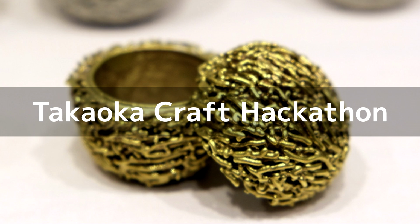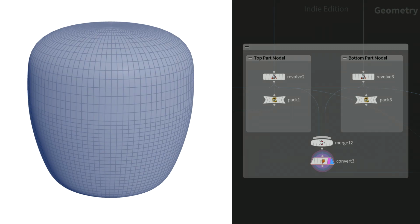The process began by creating a vase shape and then adding intricate slime mold inspired branching networks using so-called space colonization algorithms. By using the VDB workflow, I ensured the final design was both complex and perfectly suited for 3D printing. Now, let me briefly walk you through the process I used for this project in Houdini. First, I started by creating a vase shape for the vase or cup, designed to be used for the tea ceremony.